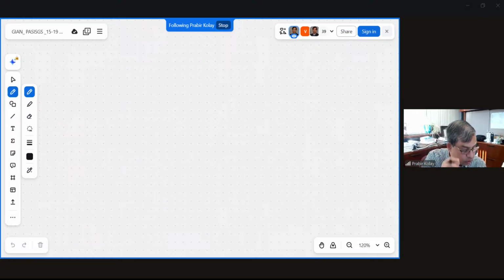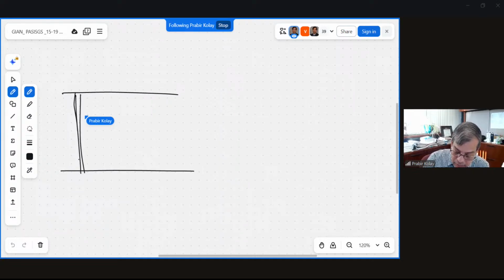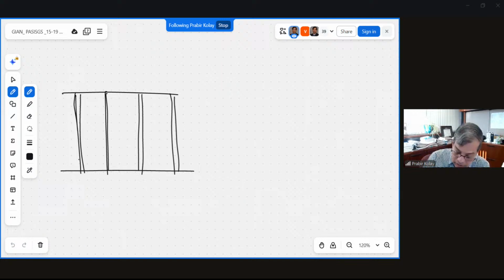So basically, what I need to do is find out the equivalent permeability. You need to understand what is happening. Just for example, this is a PVD, another PVD, another PVD like this, right? This is impervious, and the load is coming from here. Obviously, there should be some sand drain on the top. These are all clay, right? So the clay water will go in this PVD from here also, and then it will go in vertical directions.